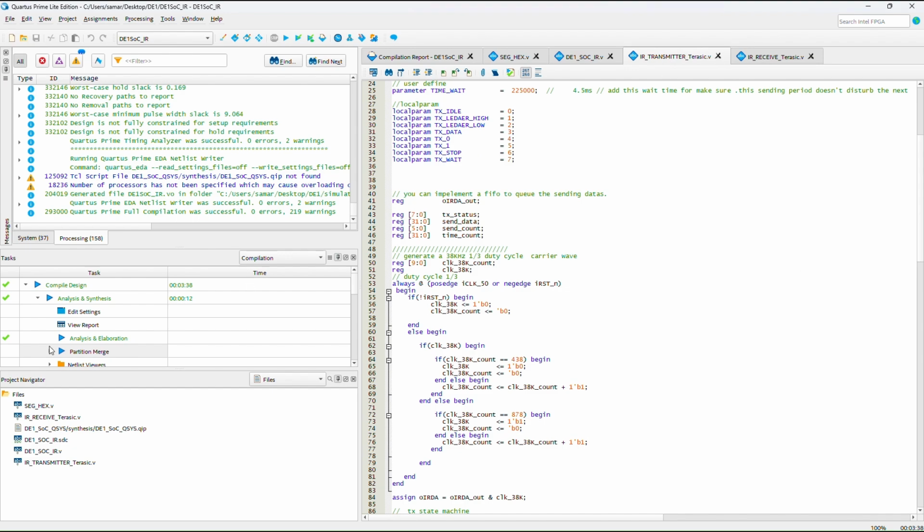Now let's jump into the transmitter. It takes the address and command byte and builds the 32-bit frame, so it's responsible for building the 32-bit frame. And as I said, when we are using an infrared transmitter or receiver, we basically flash the lights, which means that we are encoding the data that we want to send in a carrier wave, or modulating a carrier wave, which means that the carrier wave is basically a means of transport for our data. So having said that, you need the frequency for a carrier wave, right?